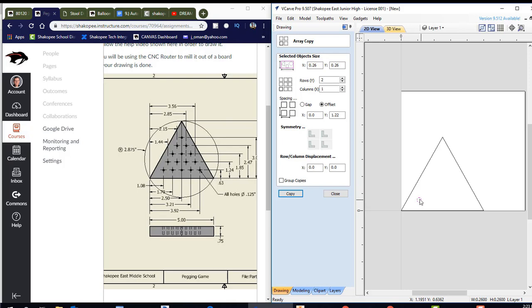I'm going to take the circle that we already made and make copies of it spaced out correctly. Follow these measurements and settings. The X spacing between those: if you take 1.79 and subtract 1.08, that's a difference of 0.71 in the X direction, so that's why I'm typing that.